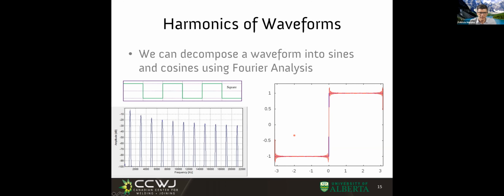And what we have here in red is a sequence of the harmonics that would form this square wave. You're going to see that it starts with something like a sinusoidal, then a dented sinusoidal when it's double the frequency. You see it in action now. And as you have higher and higher frequencies, you start to get the sharp edges. If I have an impedance, these high harmonics die.